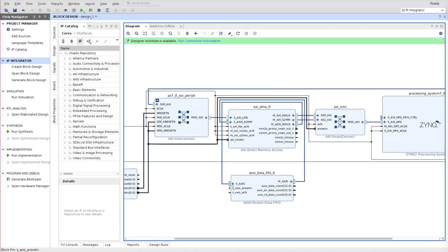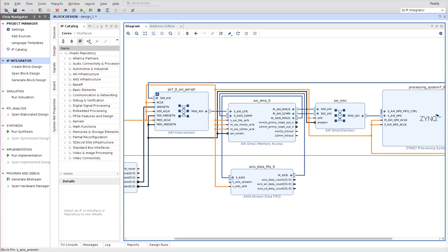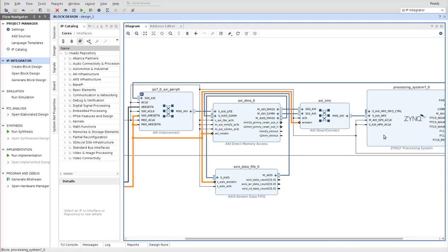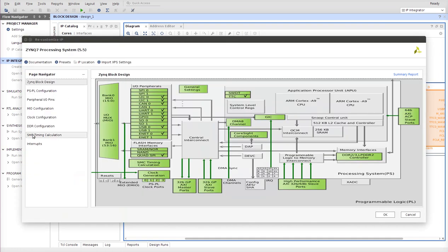And then you connect the clock with the main clock, and the same to the reset. Just to make things more complete, it's not necessary, but would be nice in the future to have, you can enable the interrupts of your project.